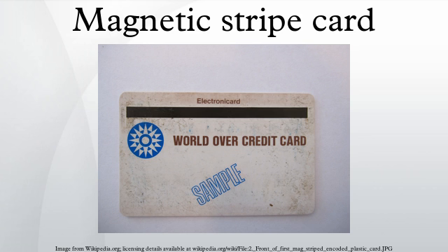to 1975. In most magnetic stripe cards, the magnetic stripe is contained in a plastic-like film. The magnetic stripe is located 0.223 inches from the edge of the card, and 0.375 inches wide. The magnetic stripe contains 3 tracks, each 0.110 inches wide. Tracks 1 and 3 are typically recorded at 210 bits per inch, while track 2 typically has a recording density of 75 bits per inch.